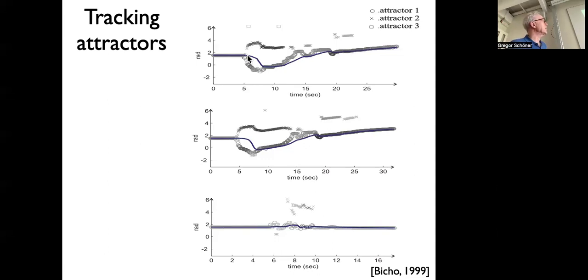You see that it does take a little while before the heading direction actually switches to one of the attractors. That's because the repeller is a fixed point, and it doesn't have a lot of rate of change. So it takes a little time to escape, in a sense, from that repeller. And we actually added noise to our control system to escape from the repeller a little bit more reliably. So that's a critical thing, that you don't do that too long.